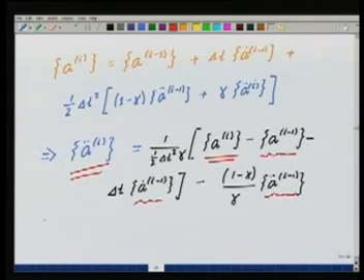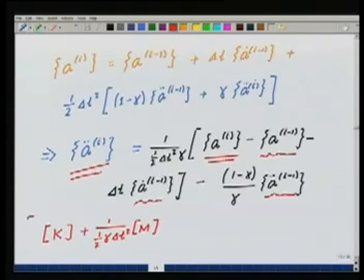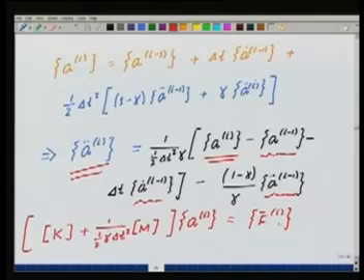So now I put this back in the differential equation that we have. Collecting terms, I will get, the differential equation at time station I: k plus 1 by half gamma delta t squared m, into a at station I, is equal to f bar at station I. F bar at station I will be f at station I, plus the contribution of all these things.